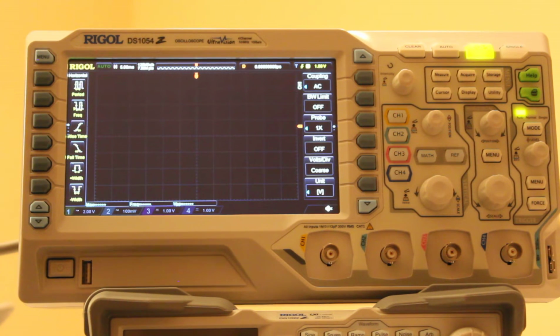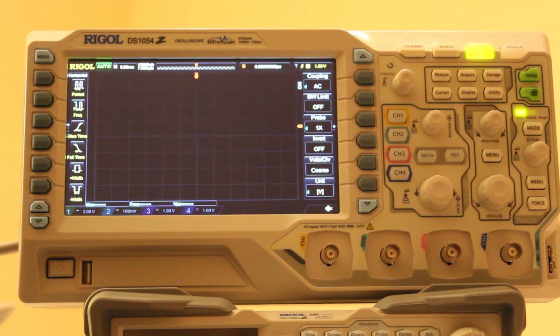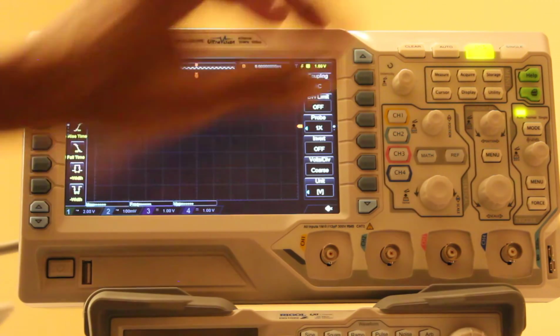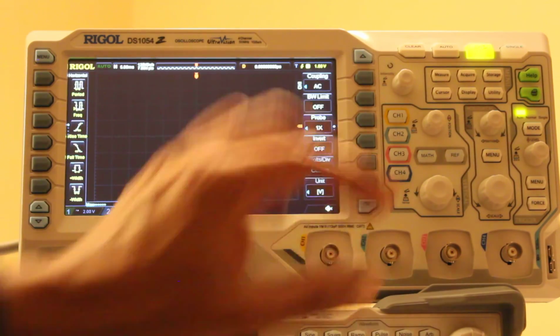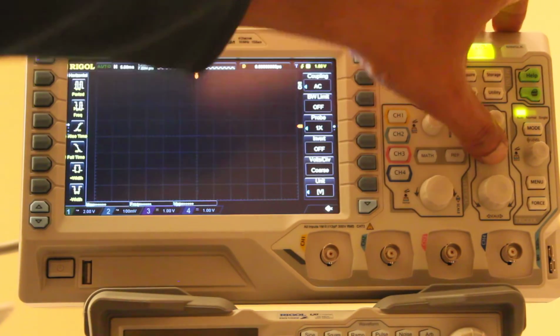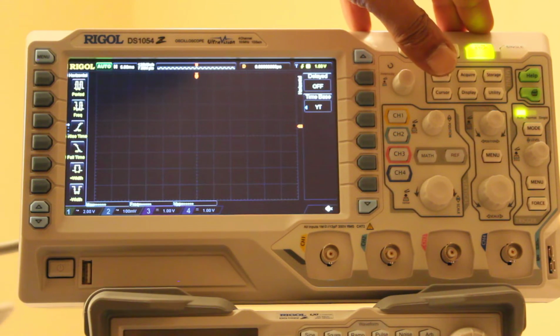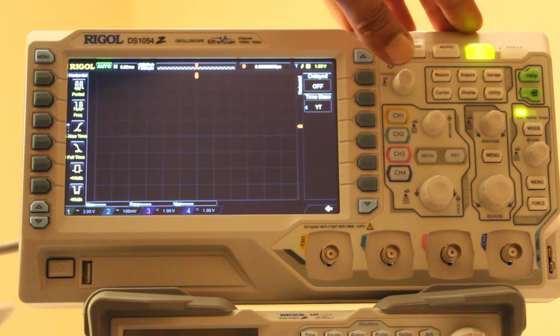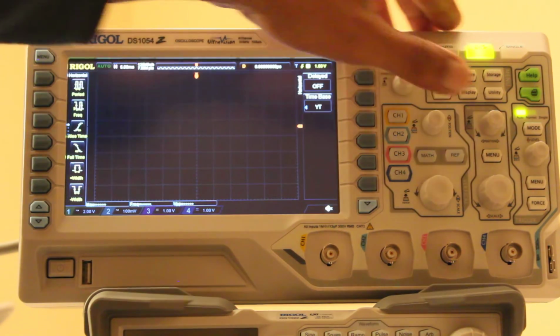So depending on your signal frequency, you will have to change the time. Most of the time the auto will take care of it, but if you want to change it to your liking, then you have to change the time base. And this is the time. It says the menu. So it says YT. Right now we will not go into any other mode, and we are not going for delayed signal or pulse, so it will be turned off.